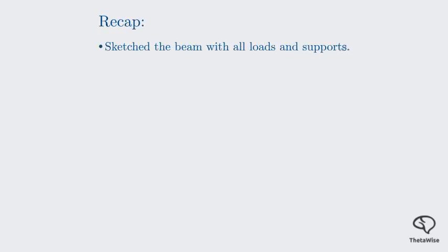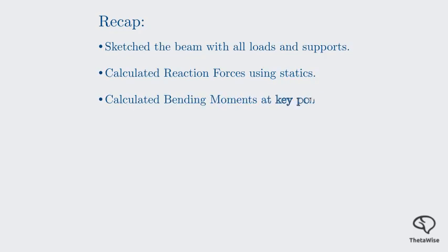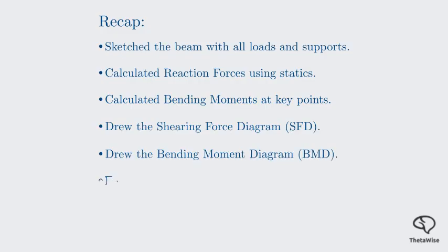Let's quickly recap what we've accomplished in this tutorial. We set out to analyze a complex beam, and we have successfully done so. First, we sketched the beam and accurately placed all the supports and loads. Then, by applying the principles of statics, we calculated the reaction forces at the supports. Next, we calculated the bending moments at the key points along the beam. We used these values to construct a detailed shearing force diagram and a bending moment diagram. Finally, we identified the magnitude and position of the maximum bending moment.